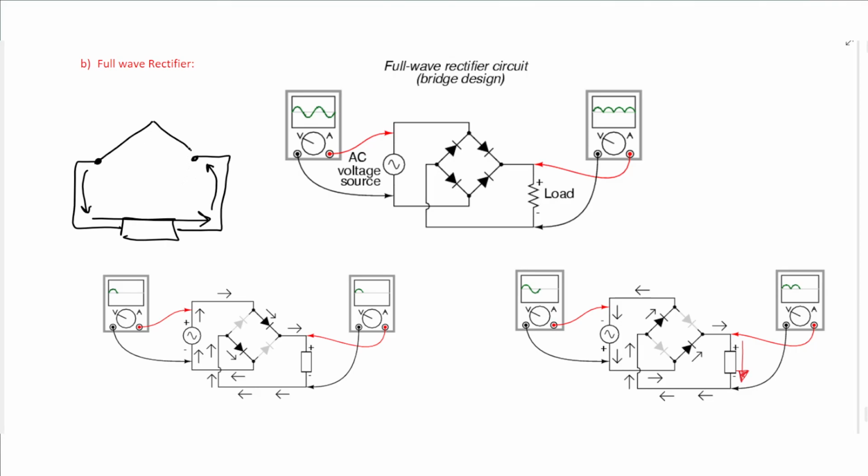You draw the diamond circuit or the diamond wires, and you point the diodes so they point with the direction of the current. So it is going in from this part, so you point the diodes away from this part. And the rest, each two diodes opposite to each other will be pointing in the same direction. This is how you draw a full wave rectifier circuit, and the output will be connected to the left out terminals. This is the input of the device. This is the alternating current from the supply.